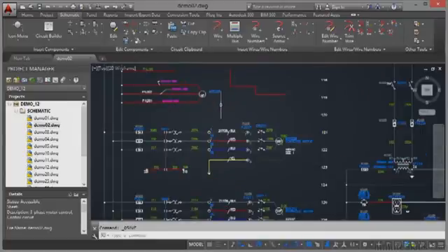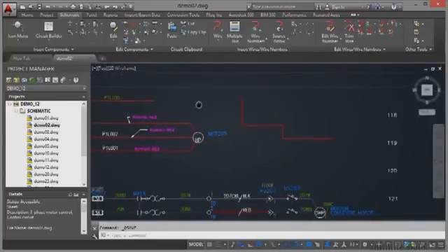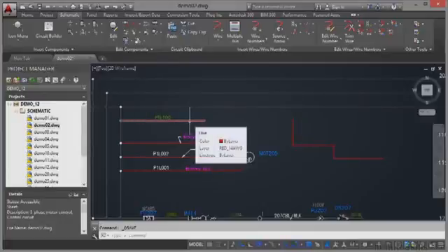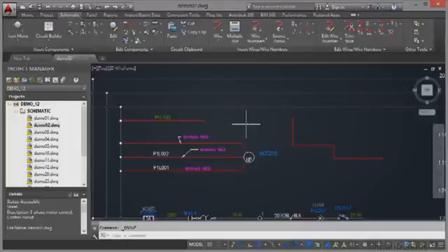What we're going to do is look at this top left corner. So I'm going to zoom in, pan, zoom in again, just to make sure that we can see all of the wires and the wire numbers. Now what we want to do is insert a couple of components here in this wire here. But we need to join it to this wire here first. We're going to utilize the wire stretch command for that particular purpose. So let's do that first.